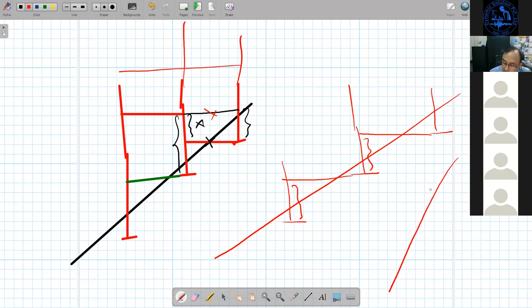In case of steep slope, even if the columns are relatively closer, you can see that it is not going to form short column. There you can provide the connection, but here it may be short column. So in that case, you don't have to provide the connection. I mean, you have to avoid short column. Somehow you have to avoid short column.